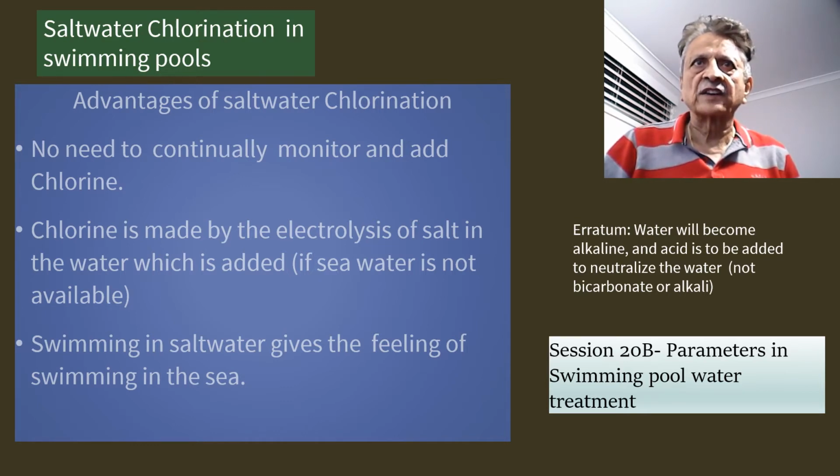a series of electrodes, which will electrolyze the sodium chloride to form chlorine, which then dissolves into the water and is sent into the pool. The amount of chlorination is controlled by the redox system.